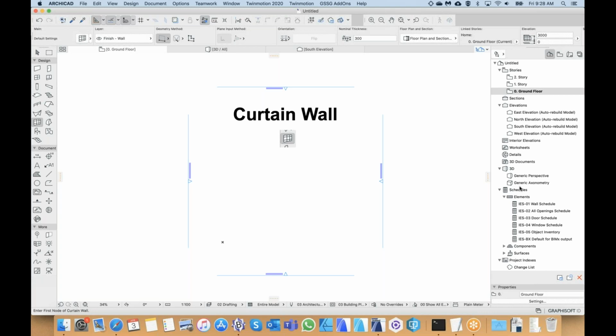Do you think a lot of you guys will be using the Curtainwall tool? Do you think your projects use curtain walls very often? So even though this Curtainwall tool is obviously for curtain walls, you can actually use it to make tiles or ceiling panels, things like this. So any kind of grid type element. So it's quite versatile. So yeah, even if you don't have curtain walls in your project, you may be able to use this for other types of things.